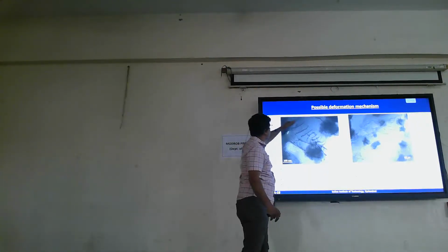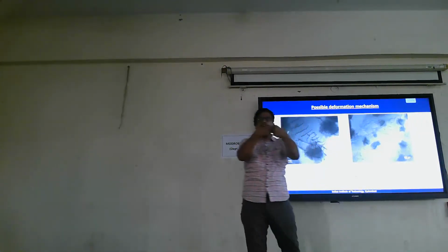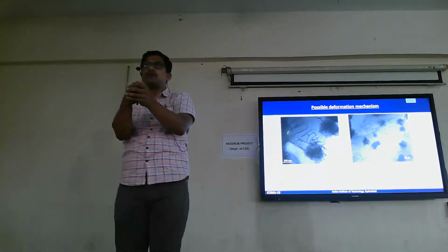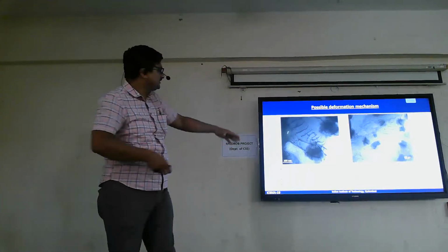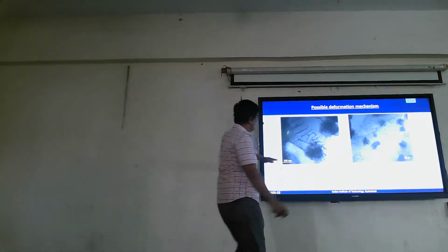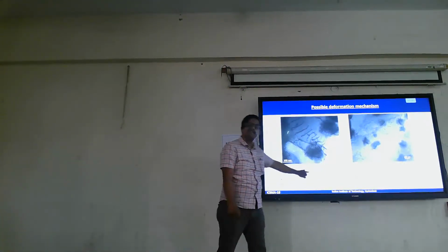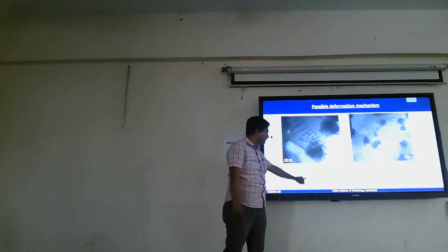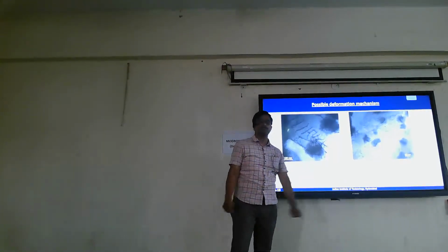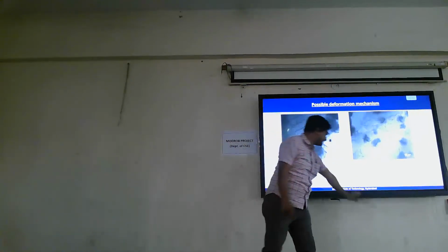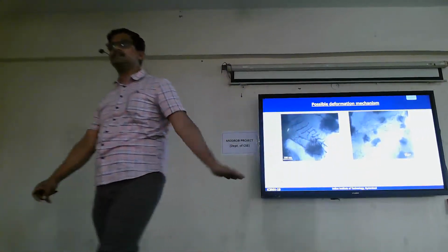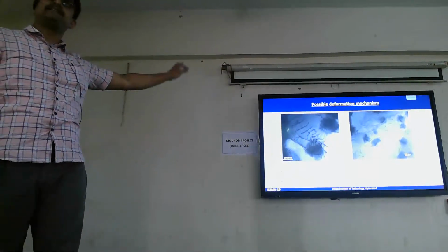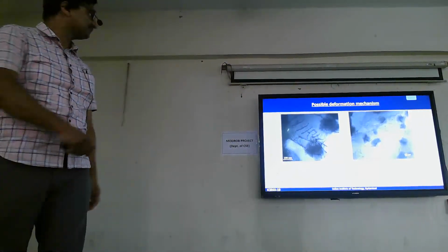The dislocations are very widely and uniformly spaced. There is no dislocation forest. The dislocations are not forming any piles or groupings. You can see the widely spaced dislocations. So the result is no significant primary creep region, no dislocation cell structure, and uniform distribution of dislocations, suggesting that dislocation glide can be the rate controlling mechanism for this material at this temperature and stress regime.